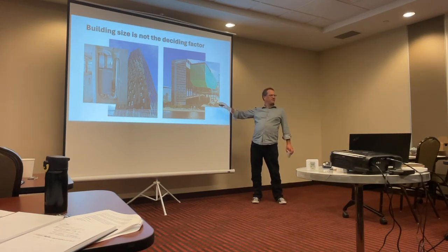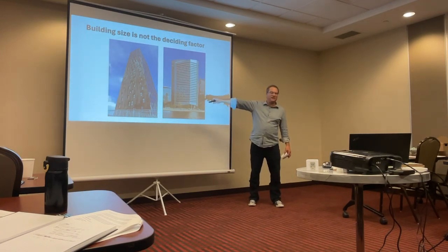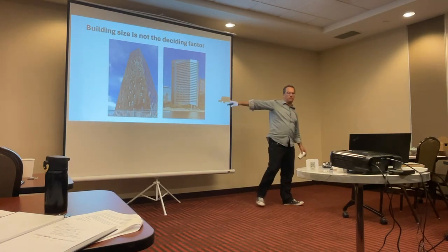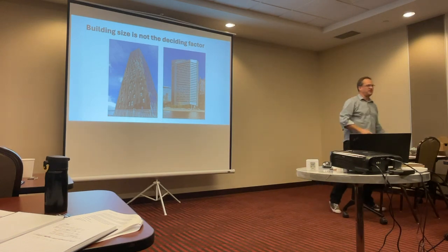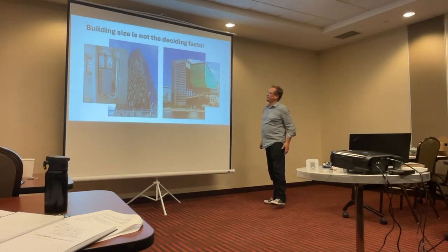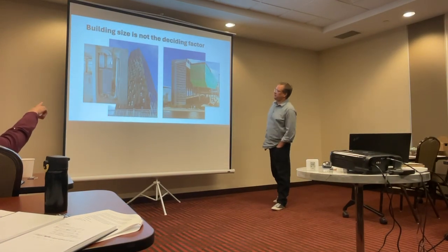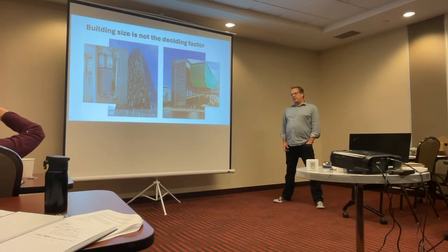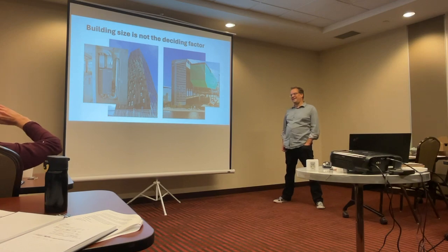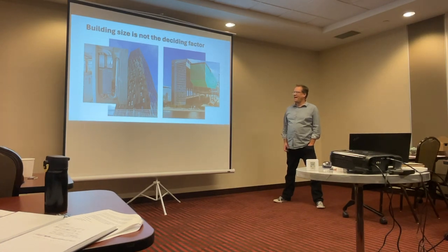Probably more robust, but what I'm trying to say here is that really good buildings, some of the best buildings in our Passivhaus world, have gone completely the other direction. So there is not a big consensus saying you gotta go one way or the other. There's one thing that you have to be really careful with decentral. One learning from this kind of project is if you have the intake and outtake onto the balcony, you have to be careful that you don't cause a short circuit. It has to be far enough outside the facade. And you gotta maintain it.